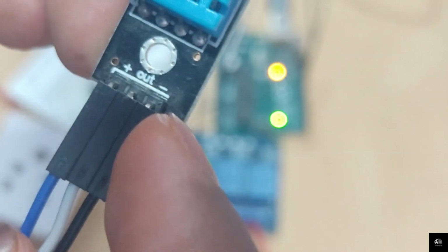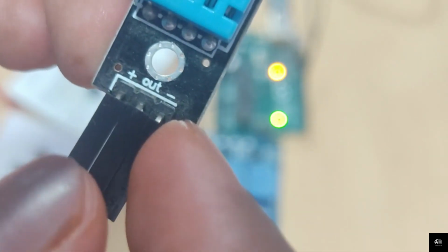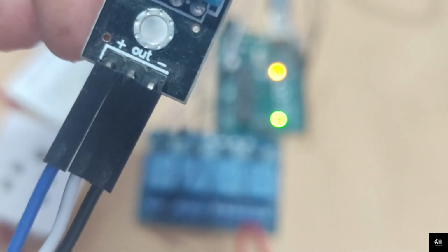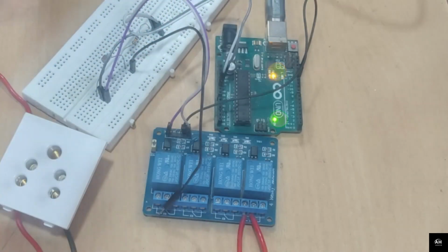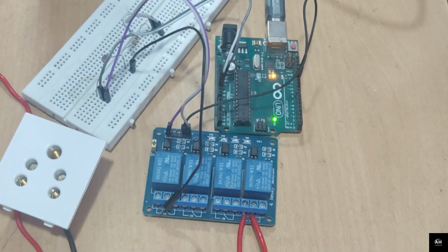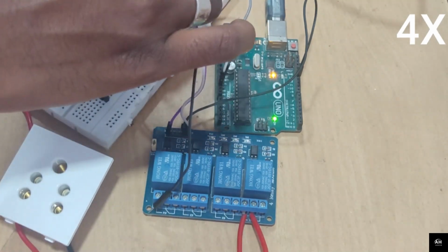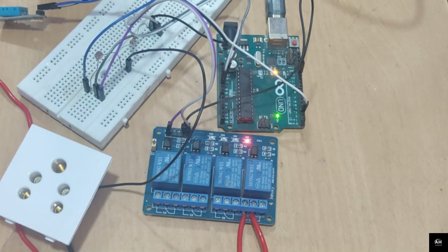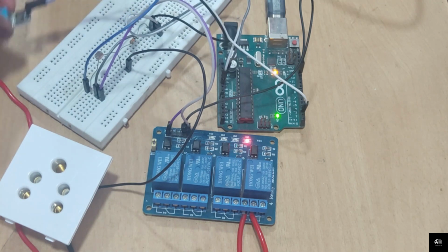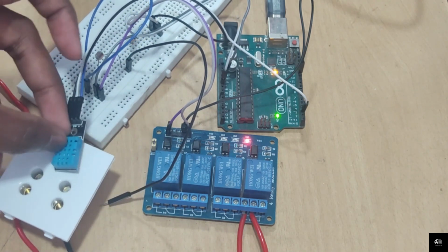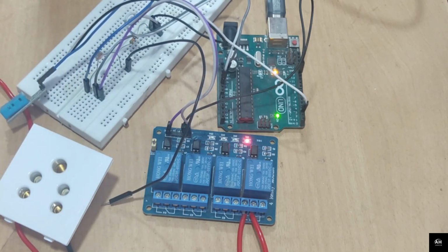And once we are connected with it, we will insert the negative pin with the ground on the Arduino board and the positive pin with the 5 volt on the Arduino board, and the out will go into the pin 2 of the Arduino board, which will be the digital pin 2. So let's just try connecting it with our Arduino. So I have already extended connections of the 5 volt and the ground onto a breadboard, as you can see on the screen. So I will just connect it over there. So we have connected the DHT11 sensor with our Arduino board successfully. You can see here is the sensor, and we have connected it with the Arduino board.